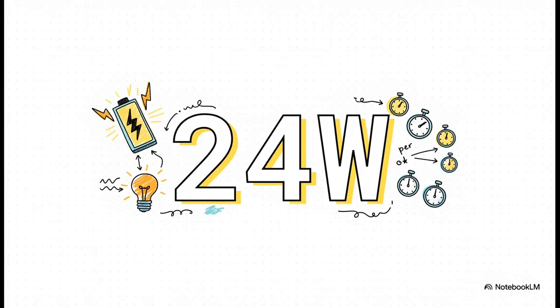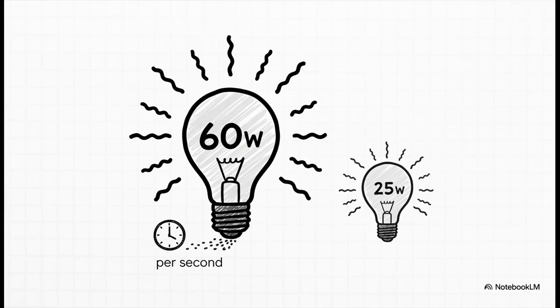Well, the math is about as easy as it gets. 12 volts multiplied by 2 amps, that equals 24 watts. Simple as that. This means our little device is using 24 joules of energy every single second it's running. It's really that straightforward. And this is exactly what that wattage rating on your light bulb means. If it says 60 watts, it's literally burning through 60 joules of energy every second. So naturally, a higher wattage means more power. That usually translates to more output, like a brighter light, but it also means more heat and, for sure, more